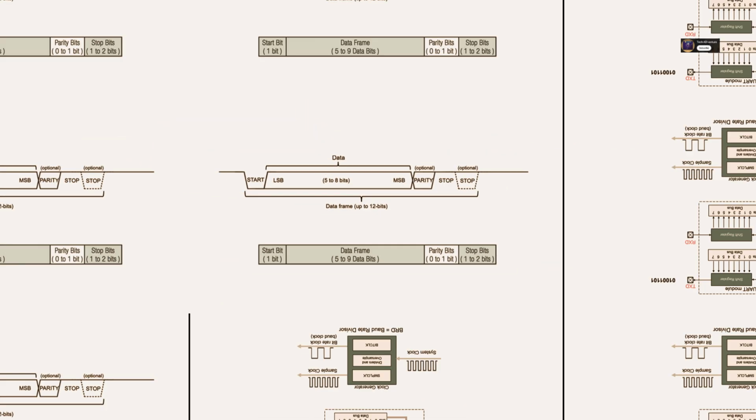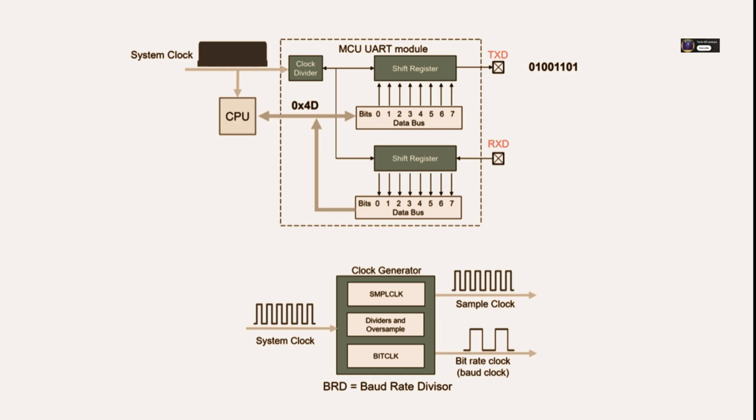Okay, LSB first. Now, we've mentioned baud rate a few times, the speed. Can we dig into that? How does it relate to the frame structure and the whole communication process? Absolutely. Baud rate is the heartbeat, really. It defines the speed, specifically how many signal changes or effectively bits are sent per second. So 9600 baud means 9600 bits fly across the wire every second.